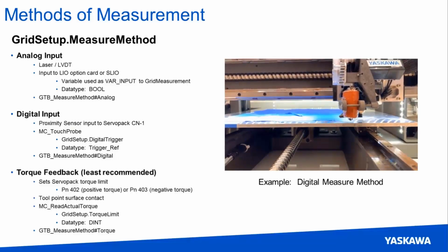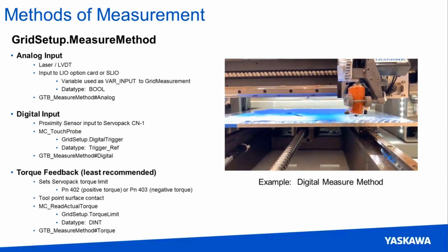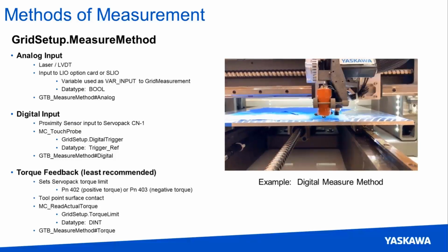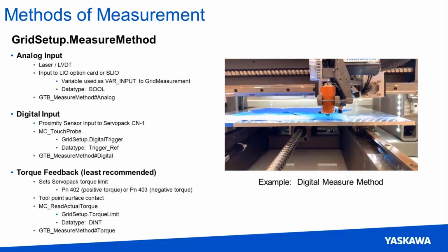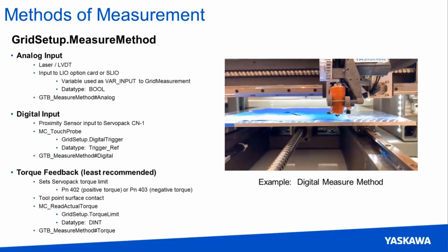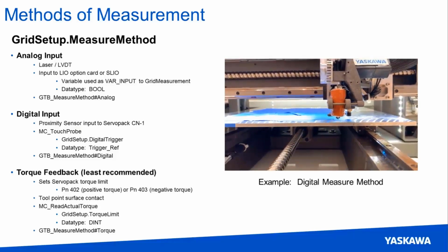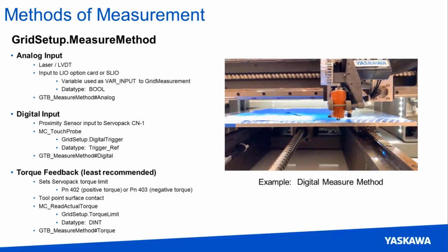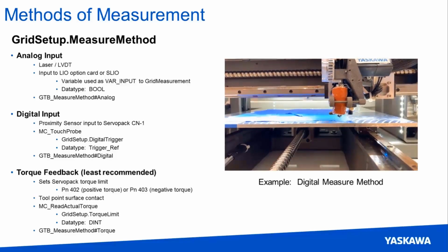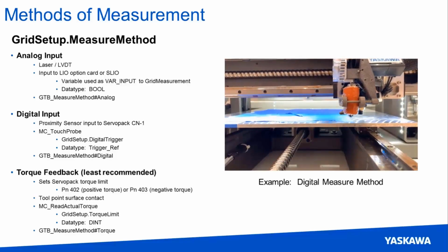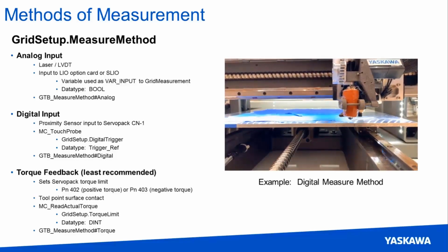The last measurement method is torque feedback. It's the least recommended of the 3, whereas it takes the longest time to set up, and there are also safety concerns that need to be taken when you're using this method of measurement. The reason being because your tool is actually going to be coming in and touching your bed, and you don't want to ruin your tool by pressing too hard into it, or your surface, or worst case, both.